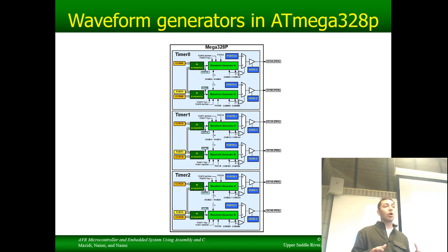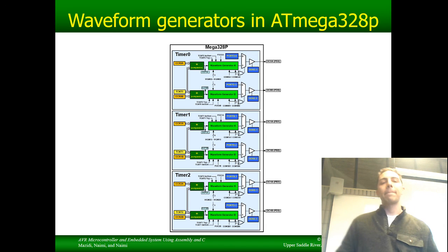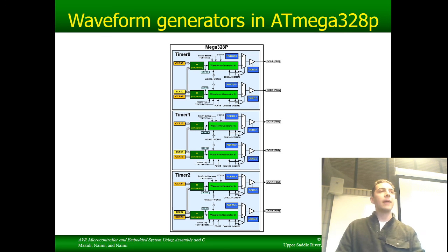So this is a much more open-ended type problem. You are given a bunch of things, told to hook them together and make noise. It should be fun because you don't have to use my frequencies to start. If you set it up correctly, you can just have a lookup table of frequencies or a lookup table of OCR values. So if you're kind of cutesy, you can set it up and you can play the piano on your little keyboard matrix as a test, or just because you want to. Okay, questions on the lab?